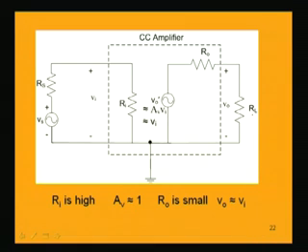where we want to get the source voltage totally equal to Vs. So now the common collector amplifier, which we have just studied, has certain specific parameter values. We have seen that the common collector amplifier has a high input resistance, Ri is high, but it has a low output resistance, R naught is low, and the voltage gain is almost equal to 1. So if I replace this common collector amplifier by its equivalent circuit having the input resistance, output resistance and voltage gain, it can be drawn like the circuit given under this dashed box.